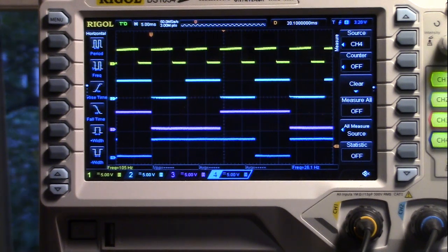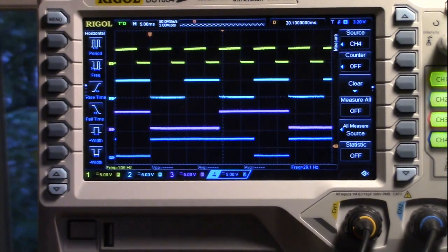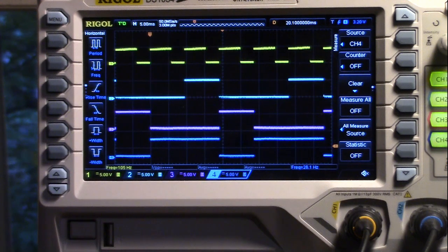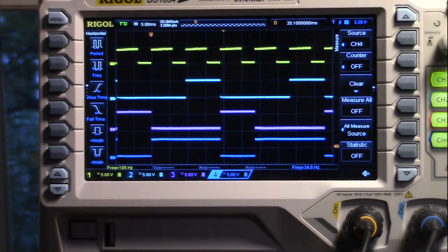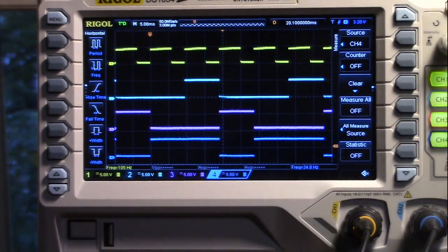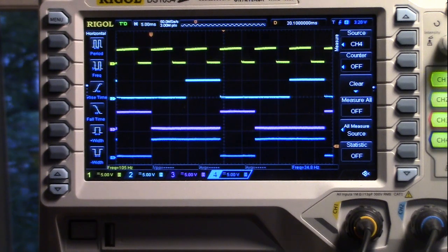How do we fix that? We go back to just looking at QB, not looking for a 1, 1, but looking for a count of 2, and we're back to a divide by 3. So this is certainly much easier to debug than having to zoom in on a 20 nanosecond pulse, and that's why we always want to use a synchronous reset rather than an asynchronous reset for doing divide by counters.